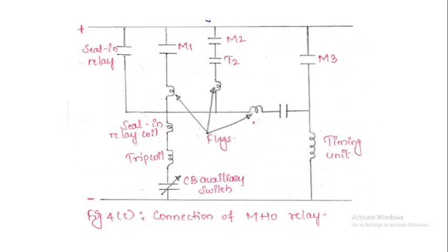So here we'll be using the 3 units now. In order to provide protection, or in order to save the contacts of the main relay, instead of M1, M2, M3, if there is a main relay contact, in order to protect those main relay contacts, which are very costly and very delicate, we need to bypass the contacts of the main relay.